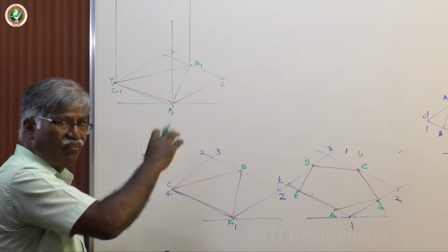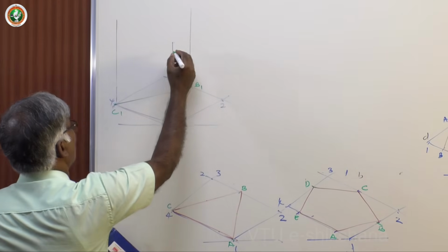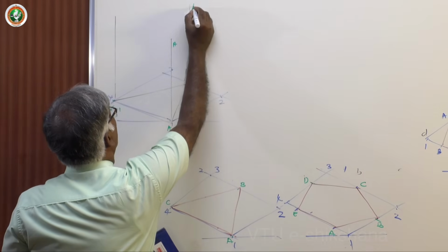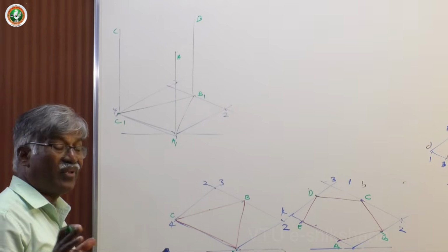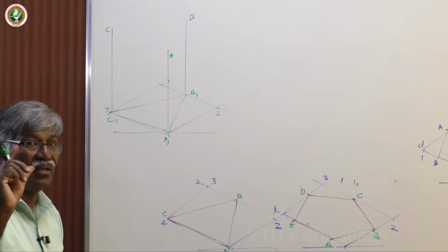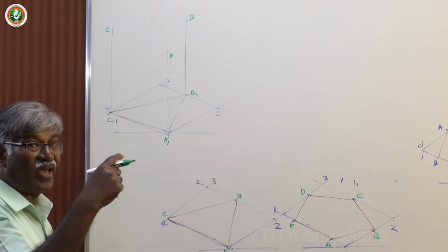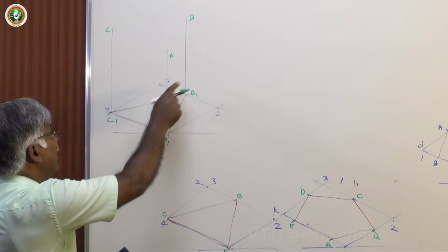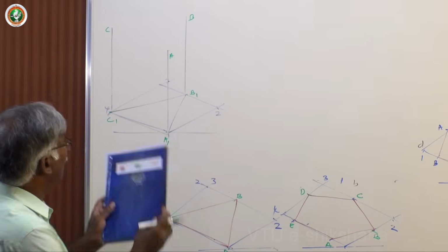If it is a prism, the base one normally will be A1, B1, C1. This becomes A, this is B, this one is C. See that all are the same height. In computer, what you have to do is keep one distance fixed, 60, then keep random vertical lines, then make it equal, or otherwise you can draw directly 60 only. Now join them.